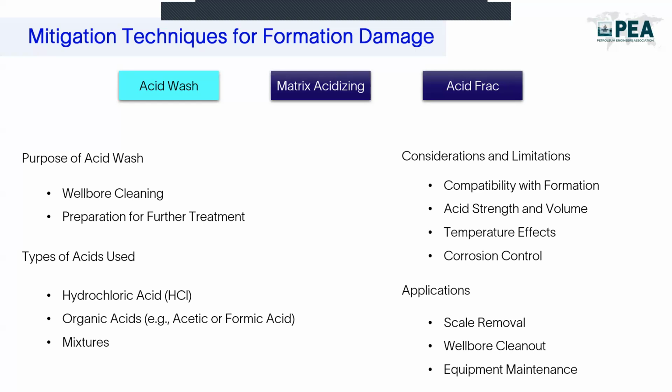So finally, for the acid wash, the main application is to remove the scale, such as calcium carbonate, iron oxides, and other deposits from the wellbore, and it's a good option for wellbore cleanout before more aggressive stimulation treatments.